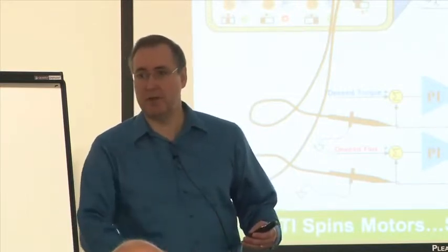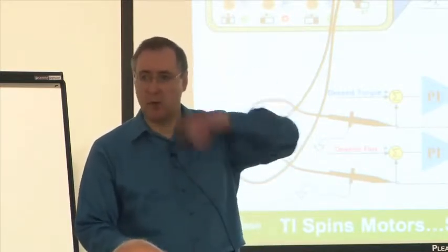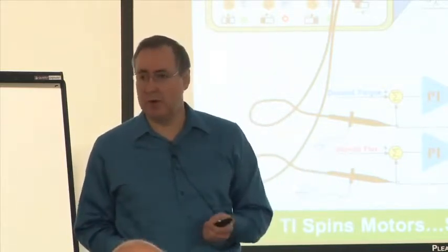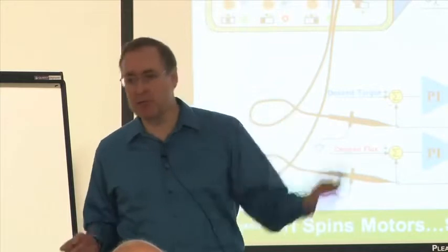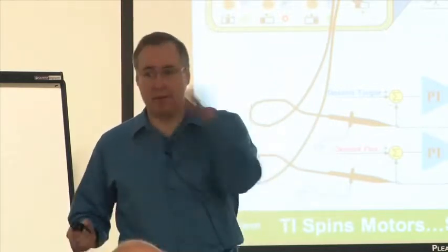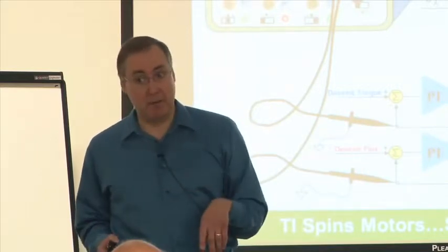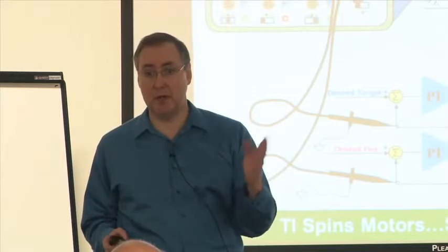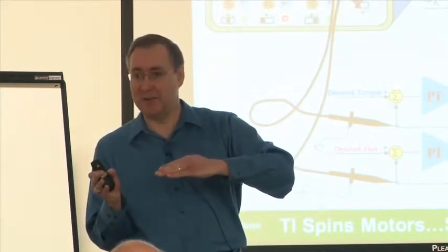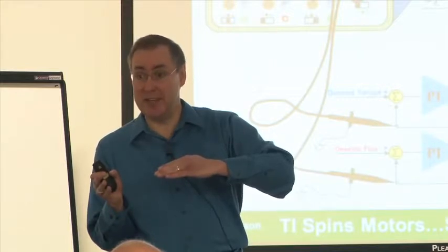You come in with something else called a starter motor. You get the whole thing working, and once it's working, you can turn the starter motor off. Same way with field-oriented control. You need to get the motor spinning, and you spin it manually just by applying a rotating vector on the motor. Keep in mind that's going to be a very inefficient operation, because the rotor will naturally want to line up with your rotating current vector, which means most of the current is going to be on the d-axis.